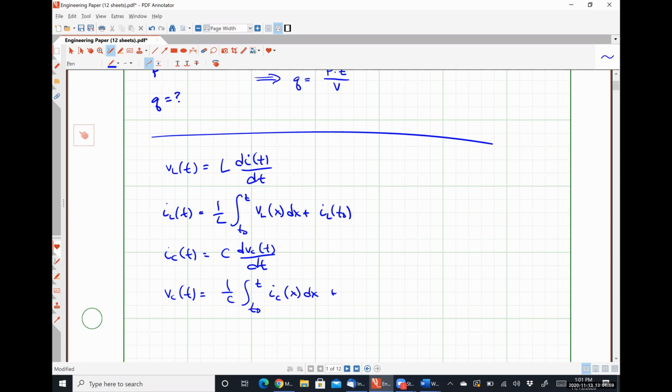It's an entirely different bag of cats, in my opinion, because for the RMS value, you're doing much more than taking the integral. You're taking the integral of the signal squared, and then you're taking the square root of it because you want the root mean squared value. Whereas in this case, we just do the like finding the area.